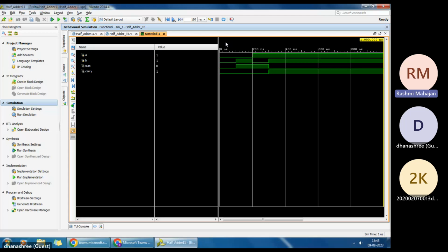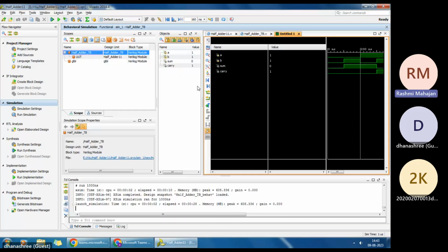These are very basic steps. Industry works in far more detail and depth, but right now we are working with the very basics. Even the simulator, we are using the inbuilt simulator in Vivado. We are not using ModelSim as a simulator. Okay, so now we will start the synthesis process. Once we complete the synthesis process, we will do the port mapping, add the constraint file, and then go for the downloading.